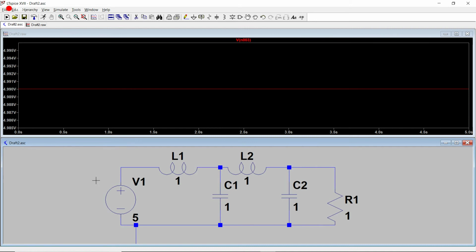And I think this has to do with some of the real world properties of inductors and capacitors. At least in theory, these should be acting as pure broken wires and pure shorts. But that's not really the case in the real world, and LTSpice is taking this into account. So when we actually measure the voltage, we get something slightly different. So that's both the good and bad thing about this method. I made some assumptions which made the problem much easier, but the assumptions do not take into account everything, and that's why we get a different voltage out when we model it in SPICE.